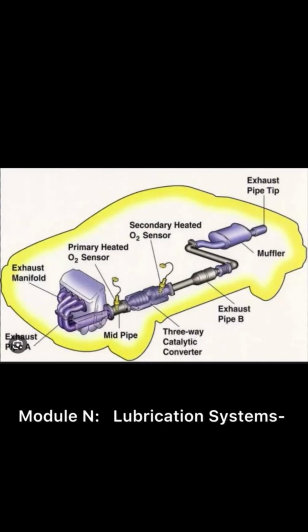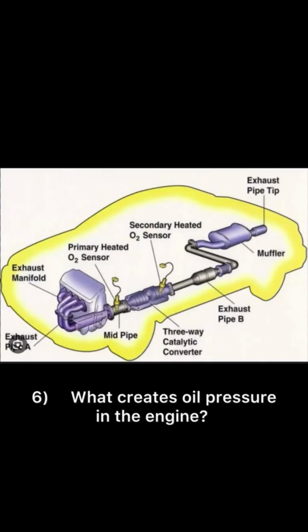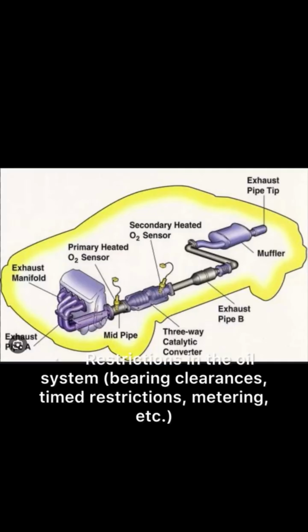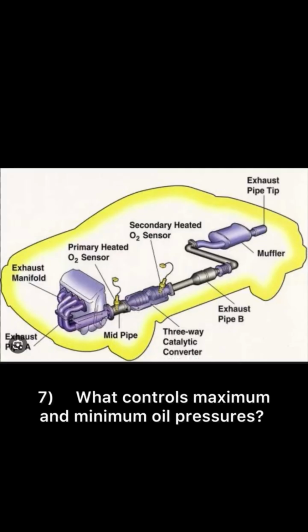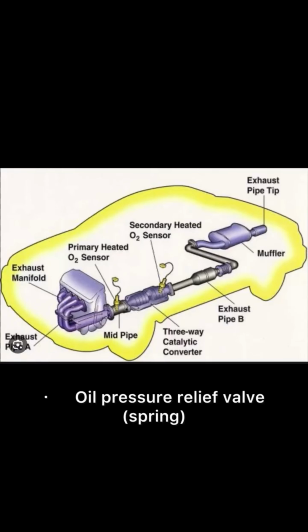Module and lubrication systems. 6. What creates oil pressure in the engine? Oil flow from the pump and restrictions in the oil system, bearing clearances, timed restrictions, metering, etc. 7. What controls maximum and minimum oil pressures? Oil pressure relief valve spring.